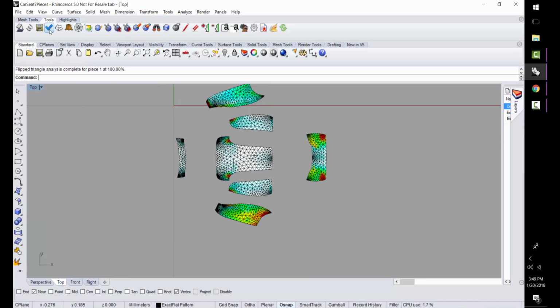So we can go around and we'll use our pre-flattener, and all pre-flattening does is basically get this flat pattern ready for optimization. It's going to take it another stage down the path to getting flat, and anything we can do to make a nice wrinkle-free, stress-free pattern going into the optimizer is going to speed up the optimization time. So in this case, I'm just going to try our fracture algorithm. And as I pick these pieces, you can see that it's flattening them out. Also, what I've noticed is as I fractured them, I've introduced some flip triangles. So let's try our pelt. There. So that's gotten rid of the flip triangles, but as I said, we haven't optimized yet.